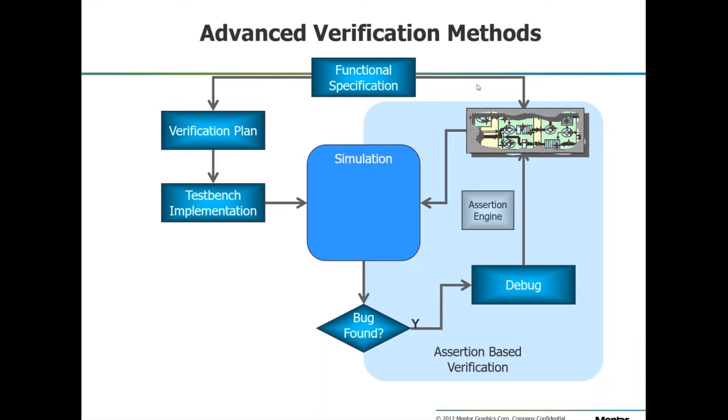So my traditional test bench is pretty much thrown away. Whereas these assertions that are bound to this block can just move in, and they don't care that they're 3 levels deep in the hierarchy, or that there are 3 of these blocks instead of 1. They're just going to do what they were designed to do, those checks, and let you know if there's any problem. So they start the process of test bench reuse.